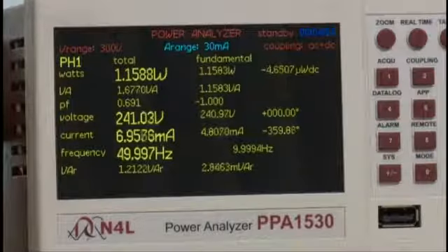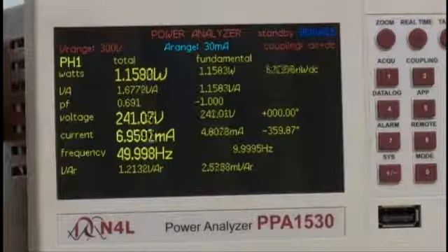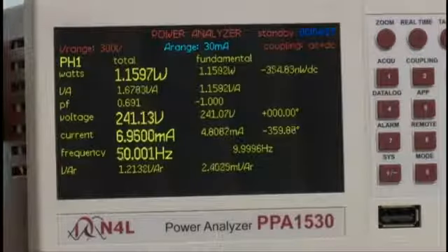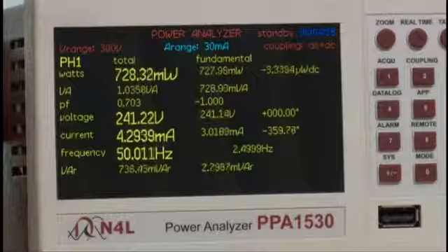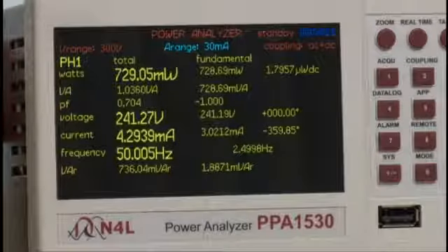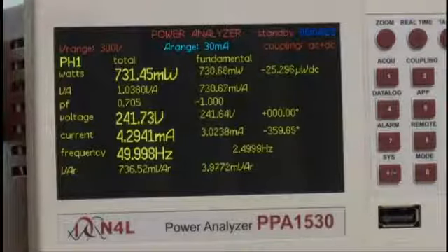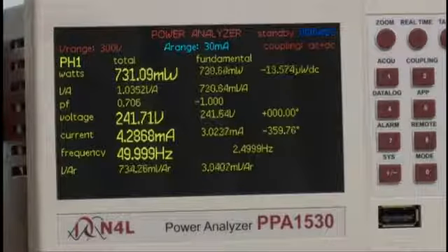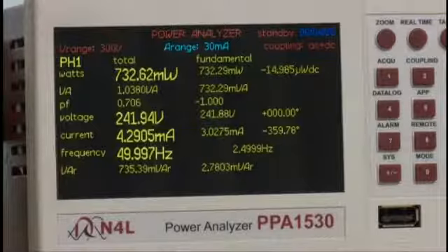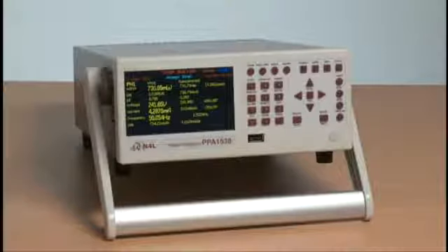the current. You will also notice that the power remains completely stable, even when I switch to a low duty cycle. And we have steady 729 milliwatts power instead of 500 milliwatts, followed by large pulses. We therefore have a solution to switch mode power analysis of low-duty standby in one instrument, with no external shunts and with no smoothing required.